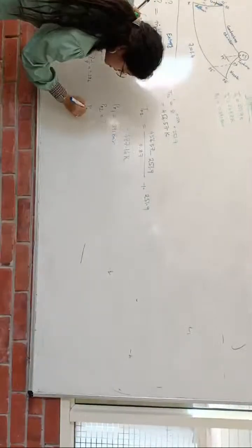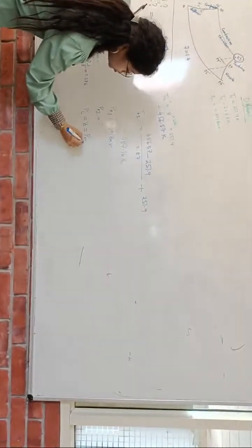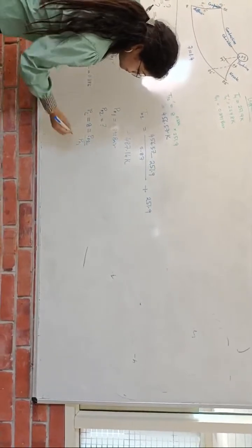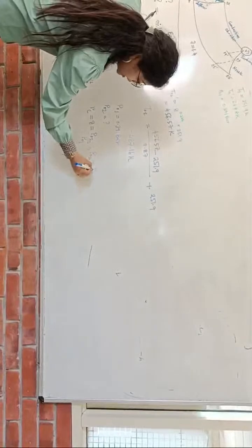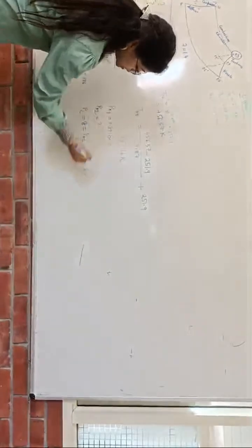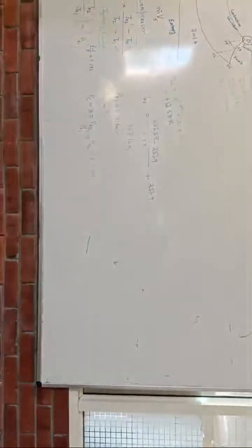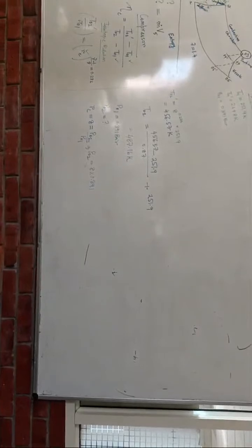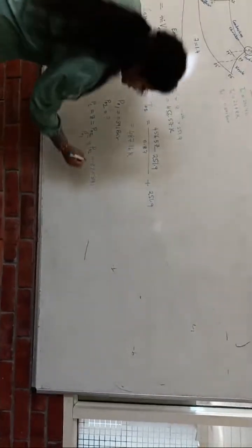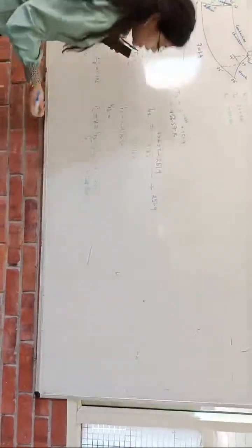How? The pressure ratio value is 8, which is nothing but P naught 2 by P naught 1. So to find P naught 2 equals 8 into P naught 1, which is 0.391. Tell me the value. It is 3.128 bar. So you got your answer.